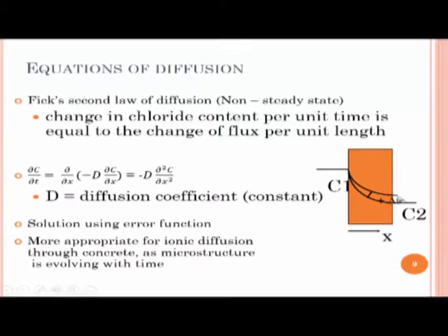Why? Because the concrete during this time has evolved, has hydrated more and more because of greater age that has passed on. Concrete is hydrated more and more, because of which it has formed a more denser structure. So you will have lesser of chlorides that actually get in with more time, okay. Alternatively, if you have concrete that is deteriorating with time, there is cracking happening in the concrete. So you can then imagine that the diffusion will lead to a higher concentration inside when the time increases. So again, you can think about it both ways.